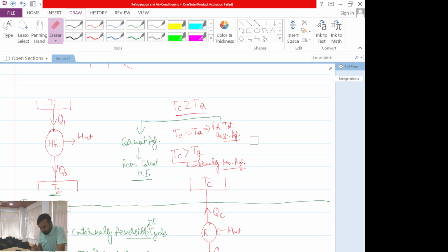Okay. So in the case of a heat pump, I will be having some space which is maintained at temperature Ts, and of course this Ts will be significantly larger than ambient temperature. For example, you are living in a place here during the winters. If we talk about Mandi also, during night time at 3 or 4 am, our temperature in December or starting of January is say less than 5 degrees Celsius. But the room we want to maintain at 25 degrees Celsius. So this Ts is 25, T ambient is 5 degrees Celsius.